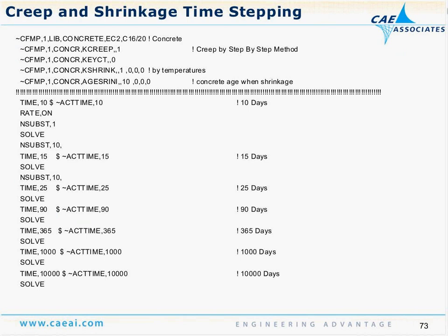And this is just an input script demonstrating where we would specify a series of times, if we're using units of days, and simply specify an activation time at the different times that we're solving for so that CivilFEM correctly interprets our material law and grabs the appropriate representation of the material properties at that particular time.